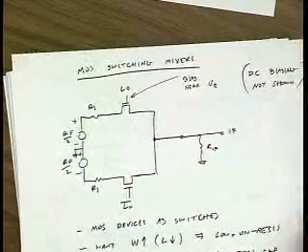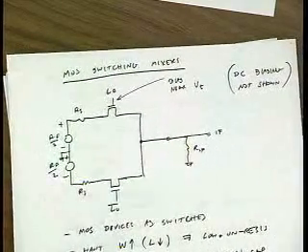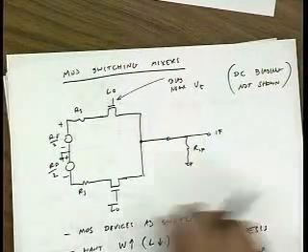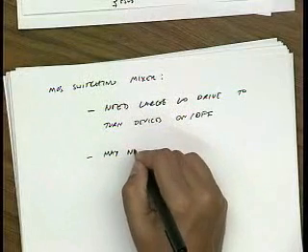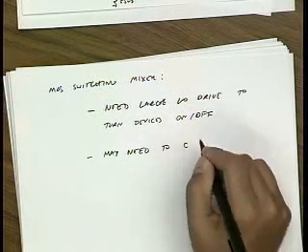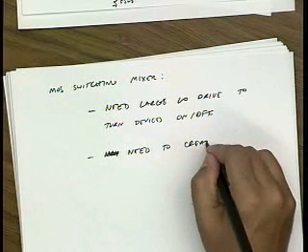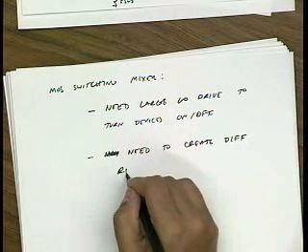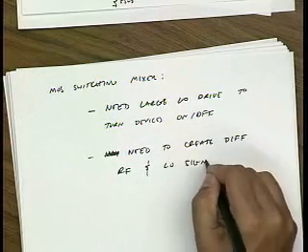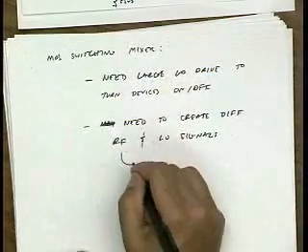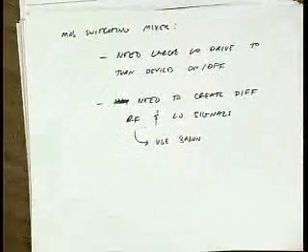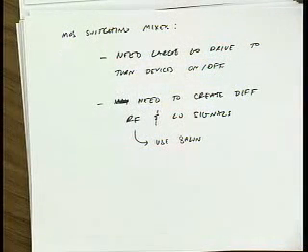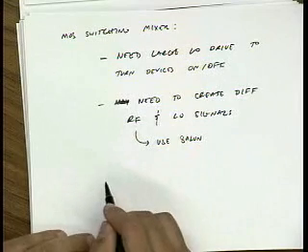All right. Any other questions? Well, another issue with this is how do we create these differential signals? In one approach, we may need to create differential RF and LO signals. And commonly we do that with a balun. And as we talked about last lecture, baluns are typically bulky and limit high frequency performance. But they're very convenient in this application.